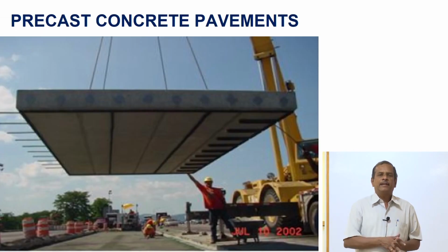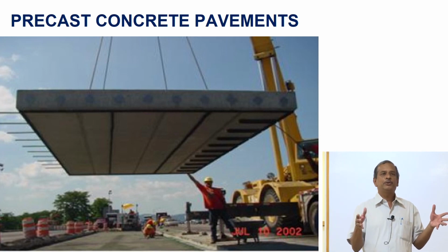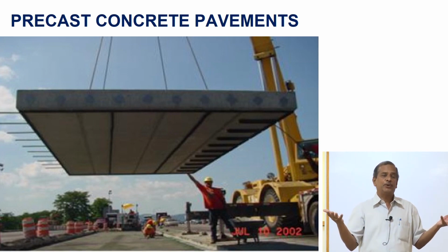So again, another thing which I want to introduce is that you can try to have a concrete pavement. As you know, the concrete pavement, you should cure it for 28 days. You can open the road to traffic only at the end of 28 days. Now, those of you from Bangalore will know, a number of roads have been taken up as white topping, a concrete overlay over a bituminous pavement. So I can construct around 300 meters, 400 meters per day. If I have to have around 200 kilometers, 300 kilometers of roads, it takes a number of days to construct these roads.